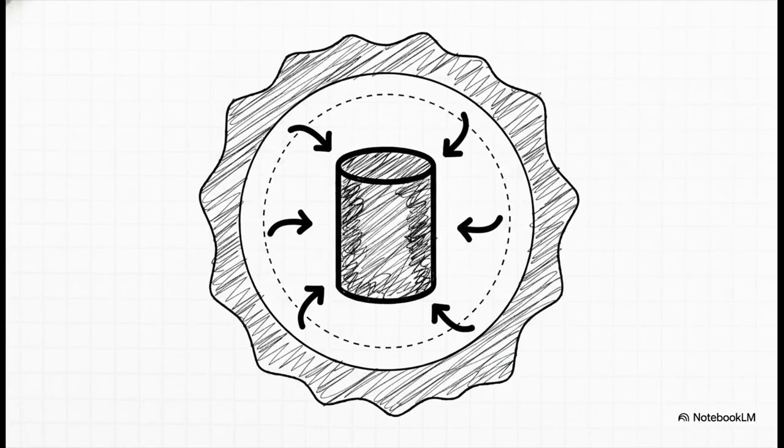Now, flip that logic for an external feature, like a shaft or a pin. To find the virtual condition at MMC here, you take the largest allowable size of that pin and you add the geometric tolerance. In this scenario, the virtual condition boundary grows larger, representing the absolute maximum envelope that pin is going to occupy in space.